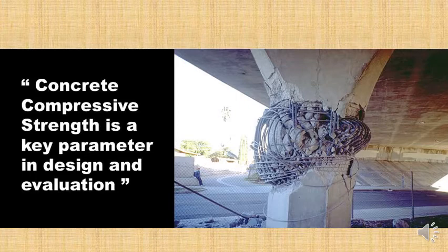But then, because the construction engineer hadn't put enough cement in the concrete, and a lot of the aggregate, particularly fine aggregate, was sitting loose, that little crack pushed it over the threshold, and then you had a compressive strength failure where the whole pier just squeezed together and the bridge collapsed.